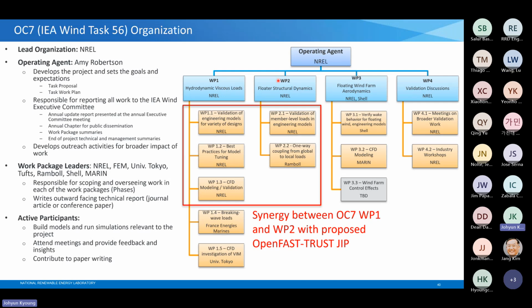I think that's representing where we are at with tank testing of flexible bodies. But we actually have a series of potential solutions. Work Package 2 is not fully defined yet. The one that's likely going to happen is, like you said, basically a couple of rigid bodies connected by springs. So it's not a full hydroelastic member. But there have also been other experiments proposed, like at DHI, where they did a full flexible spar, with a beam element that is flexing the body. So we have different options, but we still need to finalize the choice.